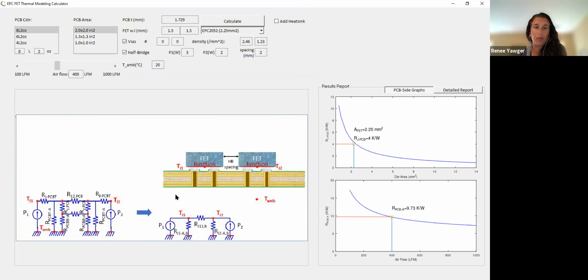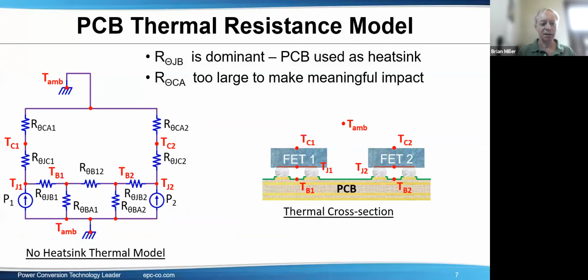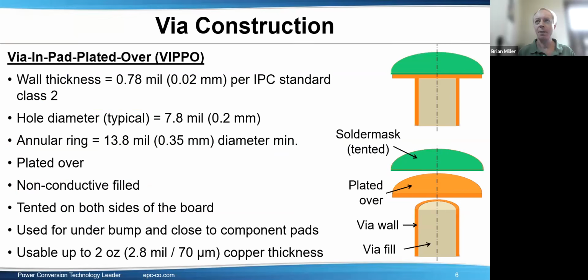How different will the soldering heat profile be of the switch that has the via in pad? It should not be different at all. That's the goal of working with it. And going back to the slide sorter and going back to the via one. Here we go. Yes, the goal is to have, when this is played over, to have this very flat, so you can't tell by looking at the board whether there's a via underneath that pad or not.